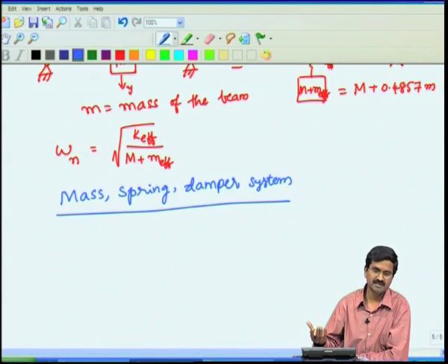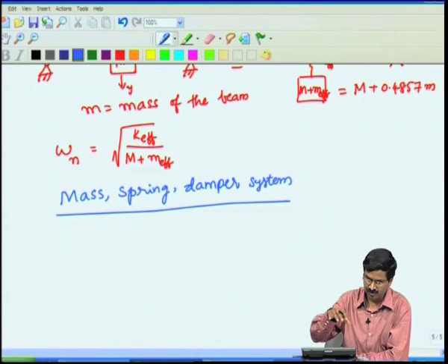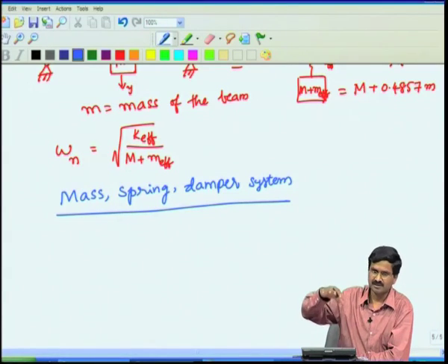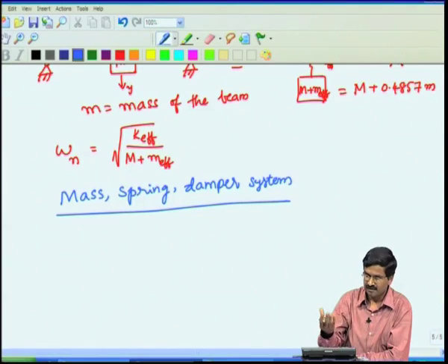It has disappeared because it has damped out those oscillation. What has damped out? In the case of pendulum, it is the viscous damping, that is the air damping around. Similarly, if I put a ball in water, if I push it, it will keep on going up and down like this, after a while it would have stabilized. Again here the water viscous damping that is acting on the ball would have reduced it.